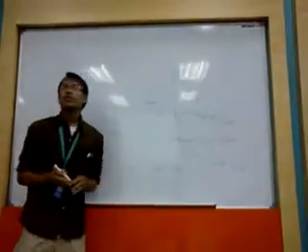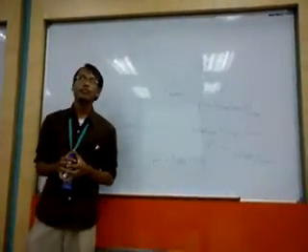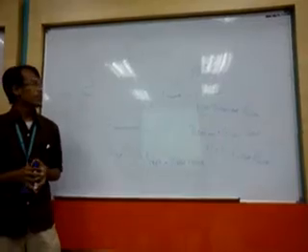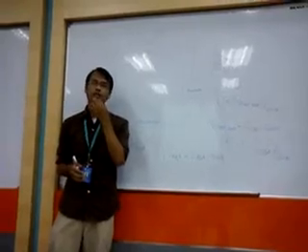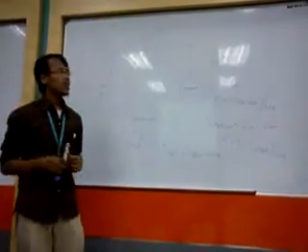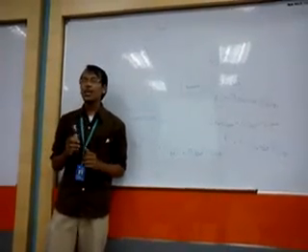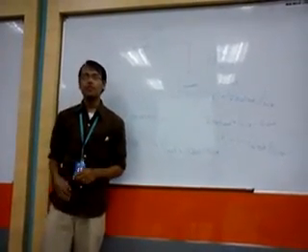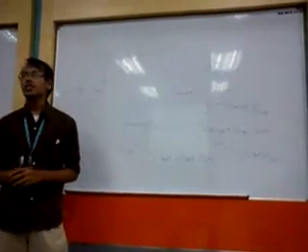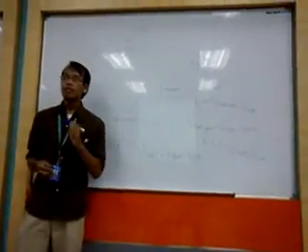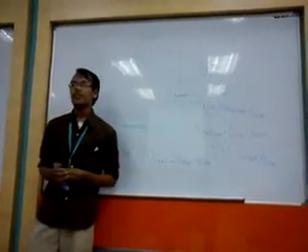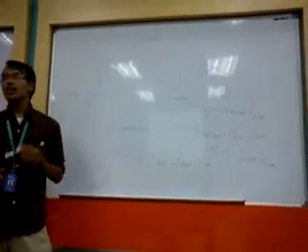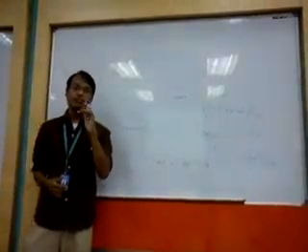QH is the magnitude of heat transfer between the cyclic device and the high temperature medium at temperature TH. QL is the magnitude of heat transfer between the cyclic device and the low temperature medium at temperature TL. Note that QL and QH are defined as magnitudes and therefore are positive quantities. The direction of QH and QL is easily determined by inspection, and we do not need to be concerned about their sign. Then the net work output and the thermal efficiency relation for any heat engine can also be expressed as